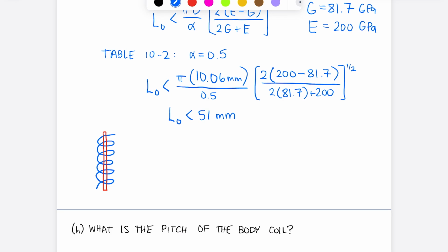Another thing that you can do that has essentially the same effect is you can take your spring and place it in a hole, so that the same thing happens. If the spring wants to buckle, it'll start contacting the sides of the hole before it buckles too far. So if those are options, that's a good way to help prevent buckling.